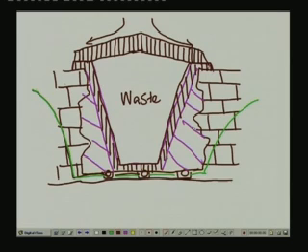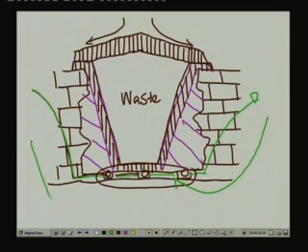Another way the possibility of leaching, as the process is called, is eliminated, is by having a bathtubbing effect by lowering the groundwater table using the series of pipes placed near the bottom of the excavation. Because the groundwater was lowered in this manner, you can see that the groundwater movement is going to be upward into the waste rather than down away from the waste.